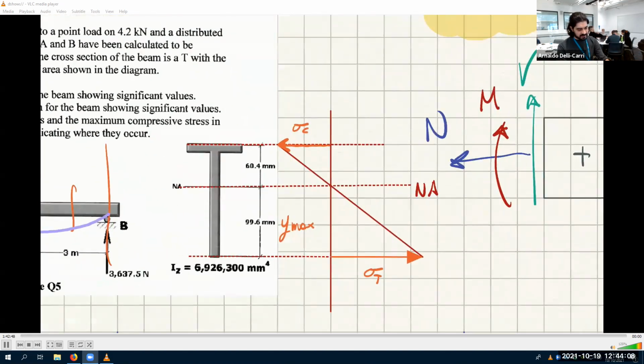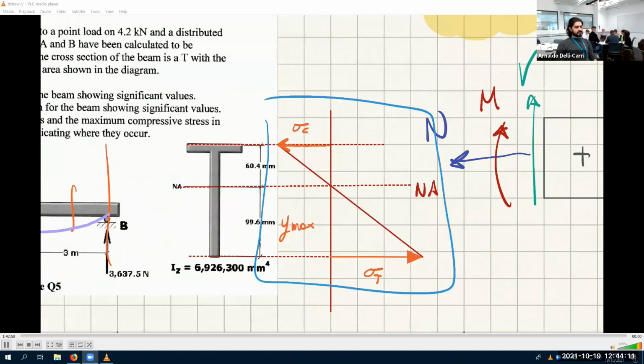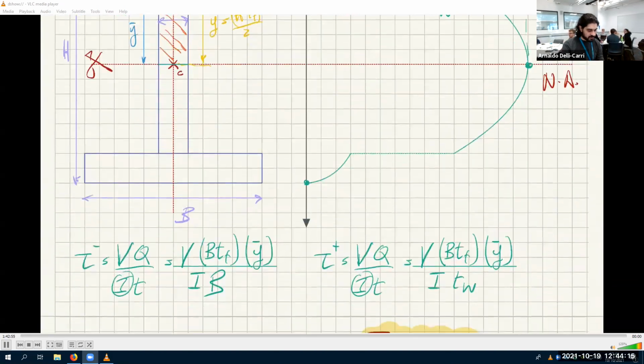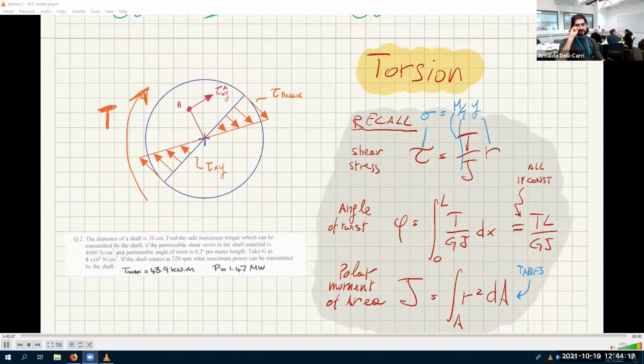See, this is the bending stress. It's a linear distribution. You have exactly the same linear distribution for twisting torque. But of course, in this case, it's symmetric because the section is a circle, so you don't have any skewness.